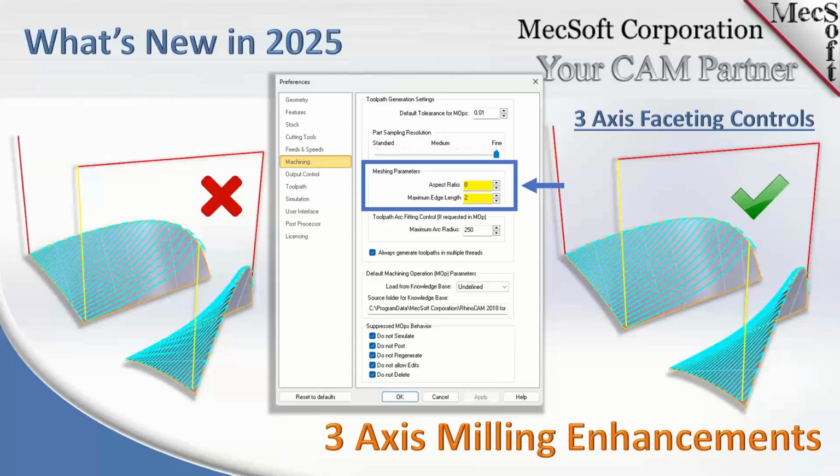But one thing to be aware of is that you can take a performance hit here. If you set up your mesh parameters to be too tight, it'll create meshes that are quite dense, and you might get a great toolpath, but it might be overkill for your application. So a word of warning there: you have to do a little bit of experimentation to see that. But what Don's going to be showing is the types of surfaces where this machine control improves the toolpath quality. Okay, thanks. All right, Don, go ahead.